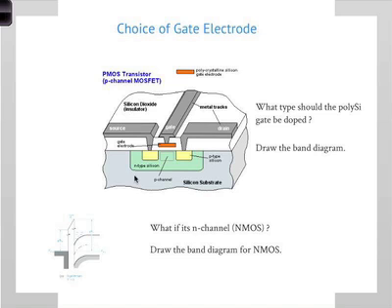Okay, this is an actual transistor, typical transistor. You have a silicon substrate, like I said. This is an N-type substrate. Okay, typically. Now you create a well here, which is an N-type well. So a small local region which is N-type, that is your N-type body or substrate for the Mosfet. Then you create the P plus source or P source and P drain. Then you have a gate electrode, and you have a channel and all that, and you have metal contacts which come to the source, which come to the drain, which come to the gate. And the gate electrode is what we are talking about.